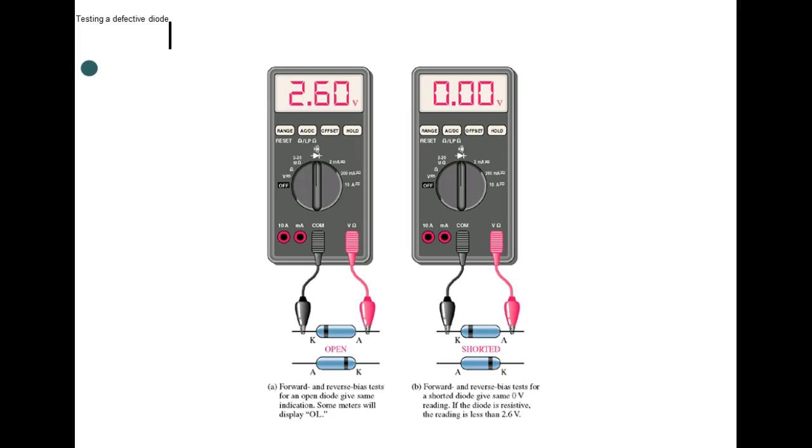So this one on the left is bad, right? The one on the right is bad. I mean, on your left. This one is bad. Why? See, it's showing me what's open. If it shows low both ways, then that means you got a problem. It's very leaky. So diodes can go bad. They can become leaky, which means they're going to conduct current when they're not supposed to be conducting current. Or they could go open, right? You understand? Or they could short. Diode short.